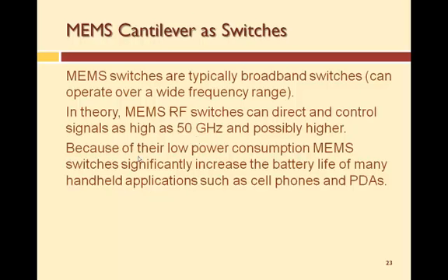Okay, and since you're using electrostatic power, which is just applying a voltage to something, it doesn't use current. Think about that. If I apply a voltage to a capacitor, there's very little current flow, only when I set up that voltage, and after that there's no current flow. So that means there's no power used, or very little power. Right? So people like electrostatic actuation because it uses little power.